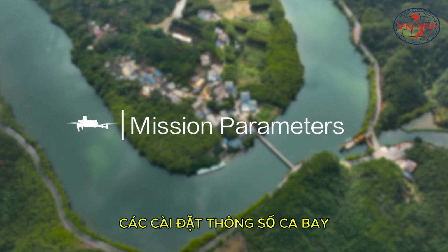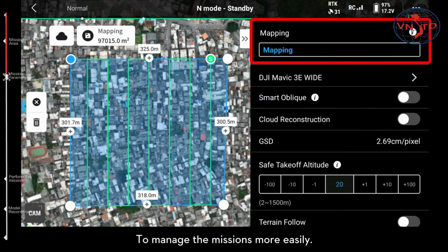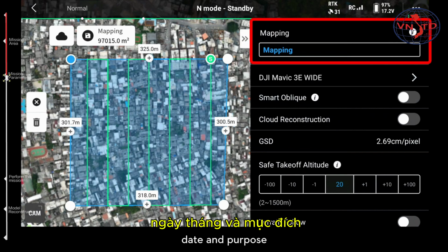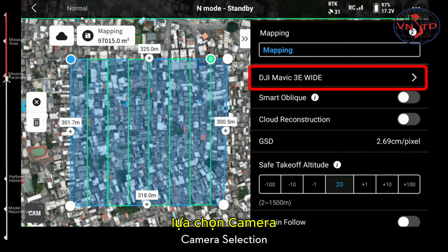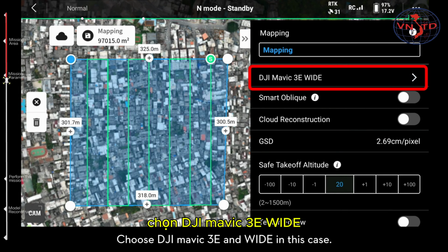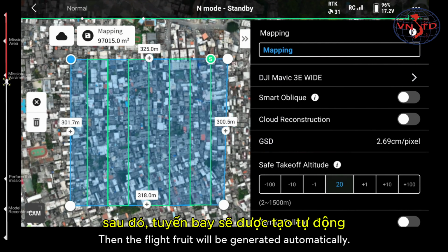Mission parameters. Mission name. To manage the missions more easily, it's recommended to name the mission by location, date, and purpose, which is the same as the folder name on the SD card. Camera selection. Remember to select the right camera at the beginning. Choose DJI Mavic 3E and wide in this case. Then, the flight route will be generated automatically.